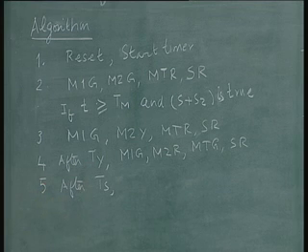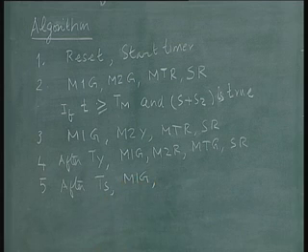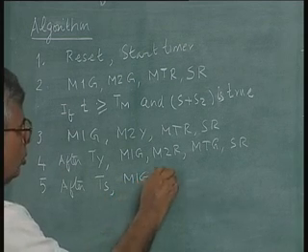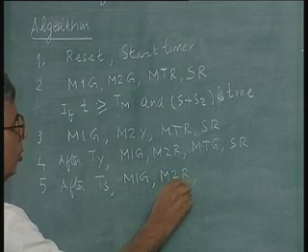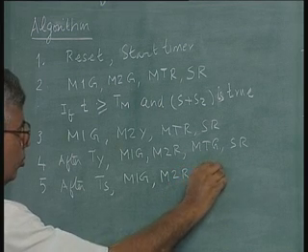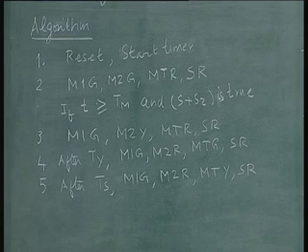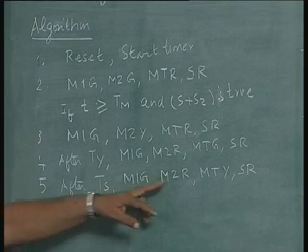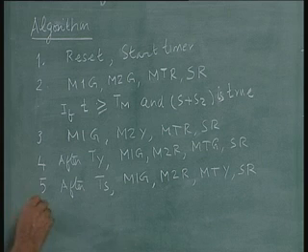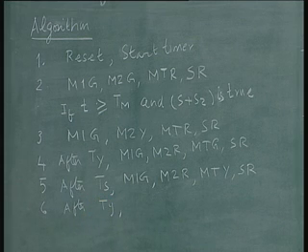After Ts, M1 continues to be green, M2 continues to be red, MT will become yellow, side street continues to be red. Now we have a yellow period again. After Ty,